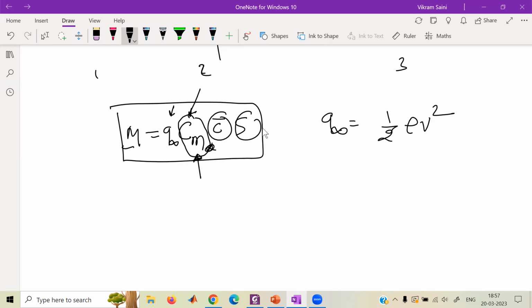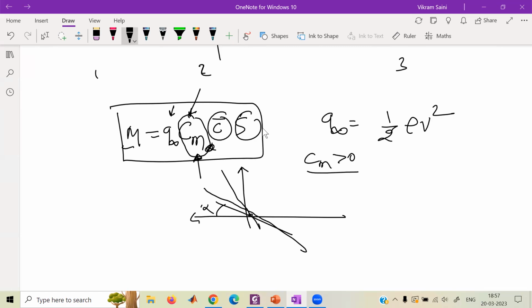Let's imagine this is the fuselage reference line and this is the wing, and you have a certain angle of attack. Now the aircraft is flying like this. If there exists a non-zero Cm, the next moment the fuselage will try to go up, then again, and it will become vertical. Your aircraft will become vertical if Cm is greater than 0 for a large amount of time. Similarly, if Cm is less than 0, the aircraft will pitch down. So you understand what it means.